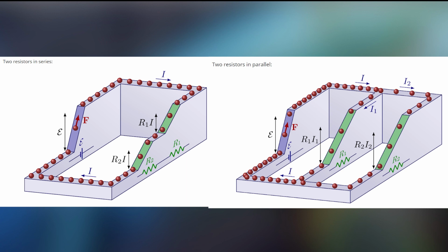And then what about an electron that's moving through bulb B, the second light bulb? How much potential difference does it have to lose? Well, again, it's 6, and so there's 6 volts potential difference over that bulb as well. So we have 6 volts of potential difference over both light bulbs, and therefore this differs from the first case where, remember, there was 6 volts of potential difference across both light bulbs, so 3 over one, 3 over the other. But in this case, in the parallel case, it's 6 over each.